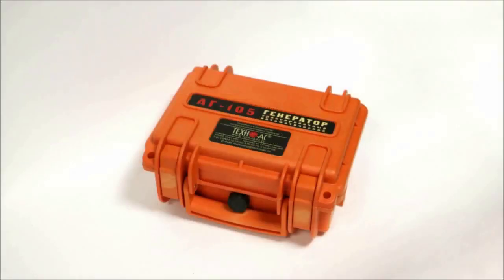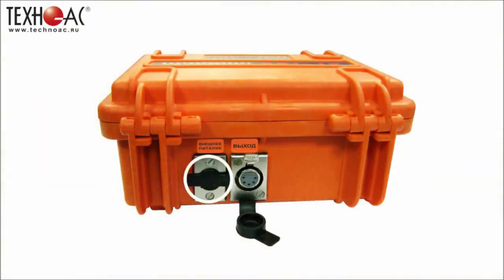supply. The transmitter generates the following frequencies: 512 Hz, 1024 Hz, 8192 Hz, and 32,768 Hz. The transmitter has a 3 contact socket with protective cover for external power supply, and a 5 contact socket for direct connection wires, external antenna, or inductive clamps. This output also has a protective cover.